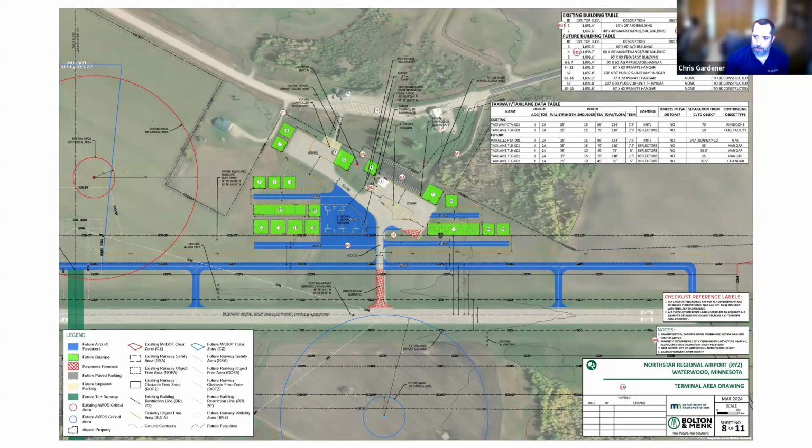So a little bit deeper dive, closer look at the building area. Be sure to include building and taxiway, taxi lane data tables. Show all nav aids in critical areas. Show OFAs, any parking areas. Show tie-down layouts, parking areas for both aircraft and automobiles. And recommendations on that stuff can also be found in the SASP document that we have.